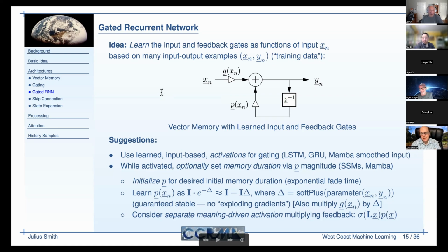Okay, so that was just a little mini tutorial on what Z inverse means. It's a pole at the origin, and it does have an effect on time. It's a time delay. And if you don't have the inverse, you have Z, then now we can say we have a pole at infinity.